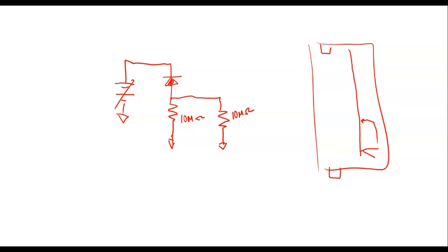So yeah, that was a true story. So what was happening is we were dividing by 10 instead of dividing by 5. That wasn't even accurate, because that's an approximation. So the Snap-on meter says about 10 meg, but when you actually measure it, it's up around 11. I don't know if y'all remember that or not, but you put it on volts. You got 2 meters. You put it on volts, and you measured the actual resistance of the meter.